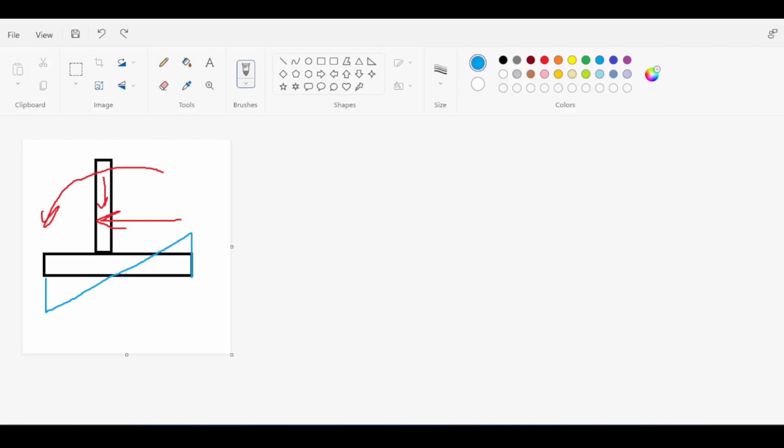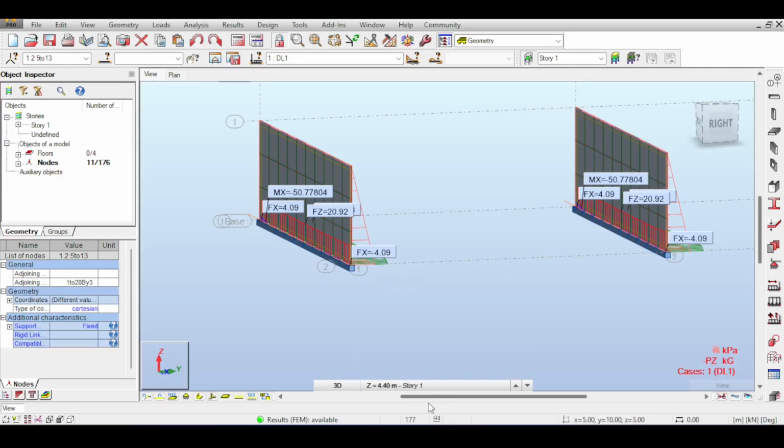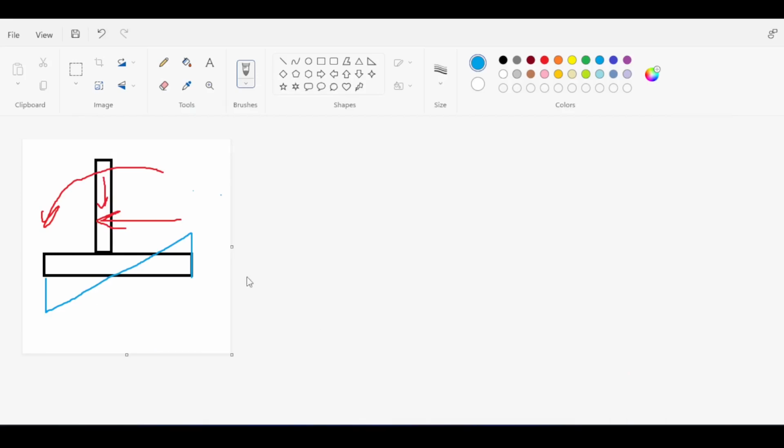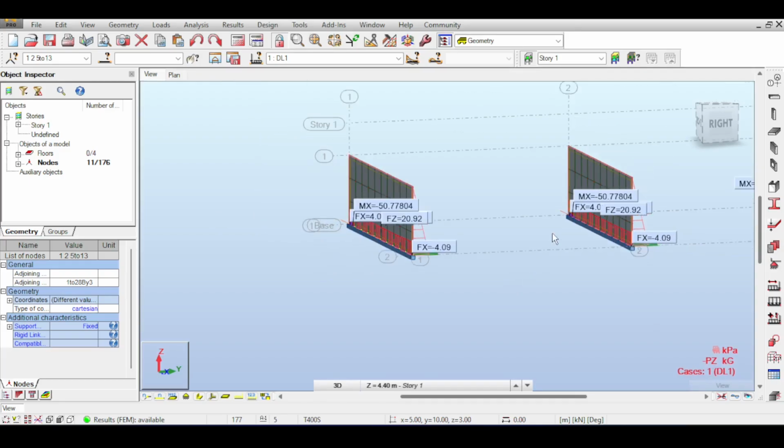Of course, I couldn't dive deep into all those points because it was the first video. Here, a shout out to our dear subscriber, Donald Khanye. I hope I'm pronouncing his name right, who actually gave me food for thought for this one. If you simply click on the foundation and design the retaining wall, you will still get a safe retaining wall, but you are ignoring the weight of the soil on the heel side, because you have soil here, basically, the soil that the wall is retaining. And this soil is an important part of the stability of the retaining wall. Now, I didn't do that in the first video because it was the first video. I cannot just overload you with information, but now is the time to actually dive deep into this.